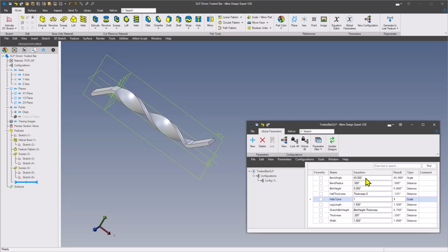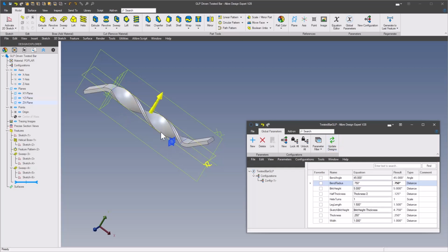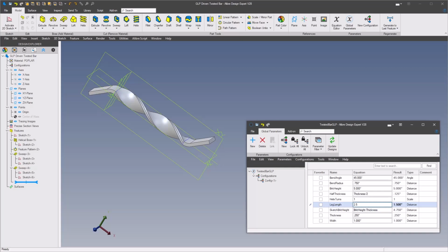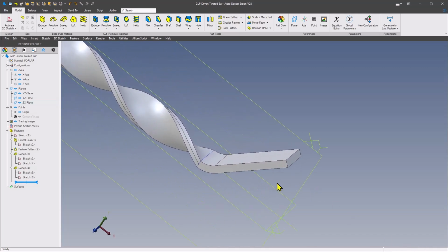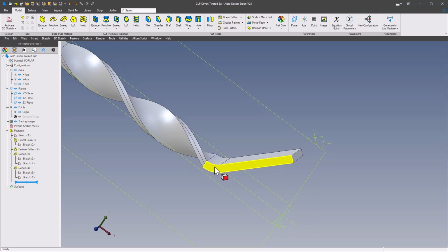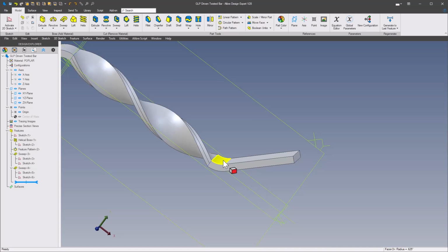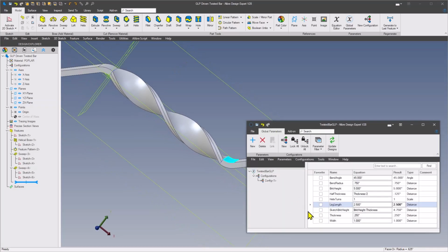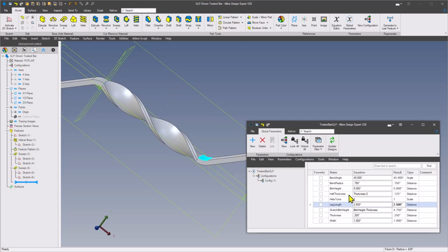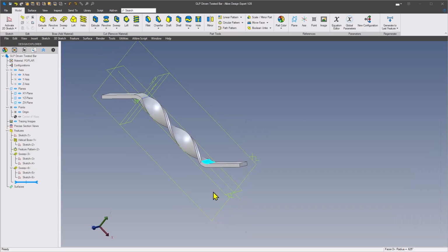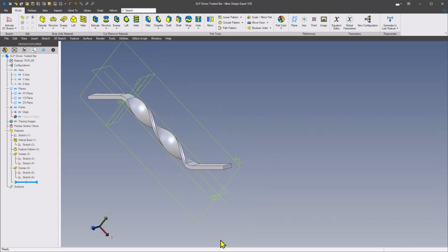Change our bend angle, bend radius. Let's increase our bend radius to 0.75 and update this. And it increased the bend radius. Get our leg length. Go to 2.5. And if we click on that, we're at 2.5. Now remember, the angle and bend radius is actually the center line. So if you wanted to have an inside radius of 0.5, then you'd have to add some more equations in here to adjust the bend radius so that you're taking into account the half thickness of the part.